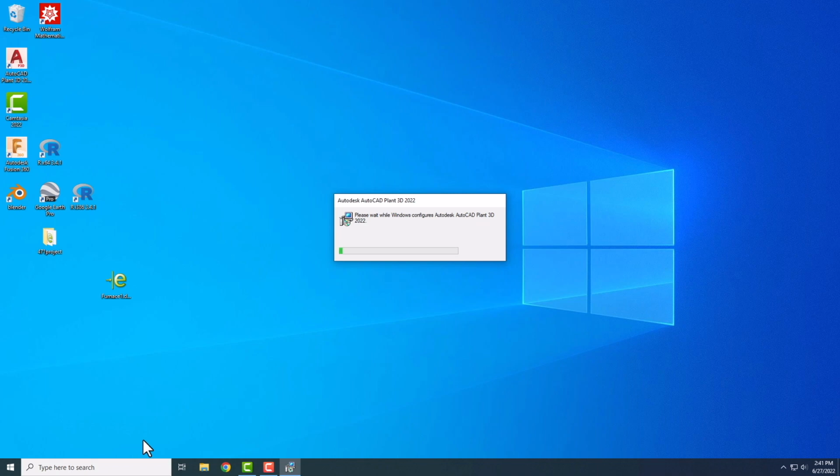And then in my following video, I will be going over a couple things that I found less intuitive about Plant 3D. Most importantly, adding your custom symbols, because you will probably need some custom symbols. The libraries will not have absolutely everything you need. I will also be going over things like off-page connectors, if you have multiple P&IDs, and some control instrumentation, how that works, a very brief overview. And I'll also give an overview of how to print your project, because it does come out on A1 paper typically, which is massive, and you'll need to shrink it down.